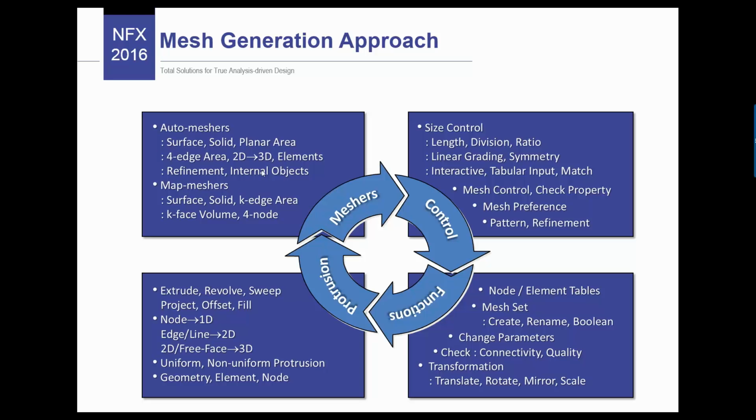So you have all these functions. You have the automatic meshes, which are here. So basically these are all the automatic meshes that you have. You have also automatic map mesh, very useful. Those are the options to control the mesh size in the model, on the lines, on the different characters of your model, to make the mesh smaller on some areas. Very, very important.